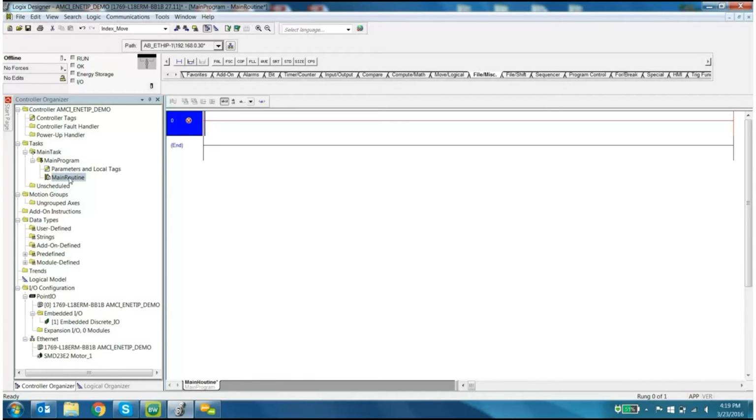When we send a motion command or any command for that matter to an AMCI Ethernet IP motion device, what we're trying to do is take a block of data which contains that command recipe, for lack of a better description, which contains that command type, whether it's a move like an absolute move or a jog move, or a clear errors command, or reset position, and so on and so forth. And then those other words that we saw in that data block, which contain the velocity data, position data, anything associated with that command, would all go down at the same time in that data block. And we typically do that using a copy instruction or a synchronous copy instruction of a particular length. So we're going to add one here to our logic.